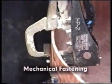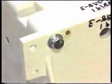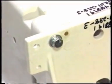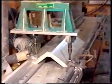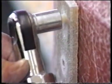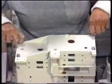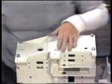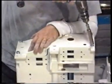Mechanical fastening involves the use of rivets, pins, bolts, and other fastener types to join composite elements together. Mechanical fastening requires precision hole making. Titanium alloy, superalloy, and stainless steel fasteners are often used, but polymer matrix composite fasteners are also available. Mechanical fastening clamping loads should be sufficient to close gaps, but not so much as to cause distortion or breakage.